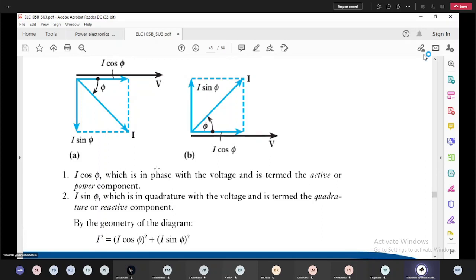What we would have, however, is that the currents, for an example, if I have got a resistor connected in series with an inductor, and that combination connected in parallel with a resistor in series with a capacitor, the current that will flow through the RL combination, so the resistor and inductor combination, will be a lagging current by a certain angle phi.